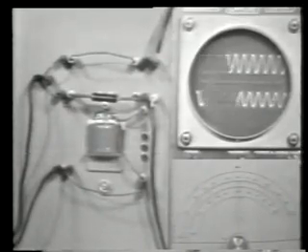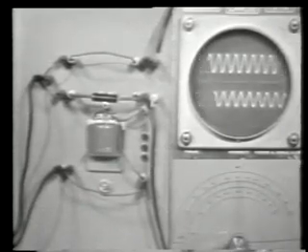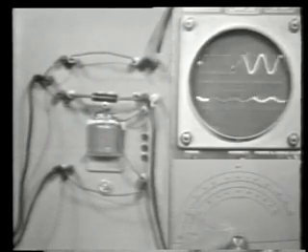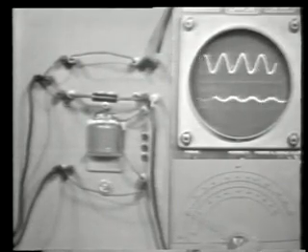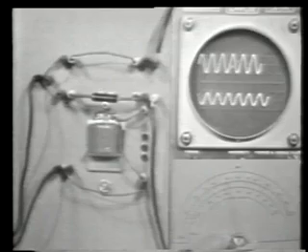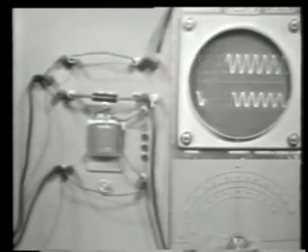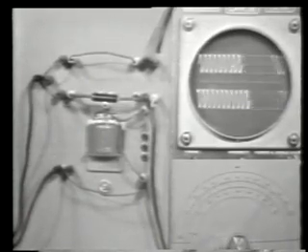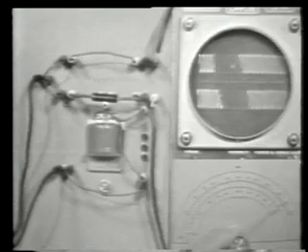Okay, let's check this out now with our demonstration. Now, as I vary the input frequency from a low of about, let's say 200 hertz, you can see that nothing much below about 600 hertz, which is at this point, is getting through our filter. Frequencies above 600 hertz are passing through, though. We're passing the high frequencies.